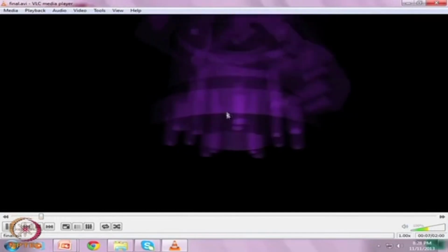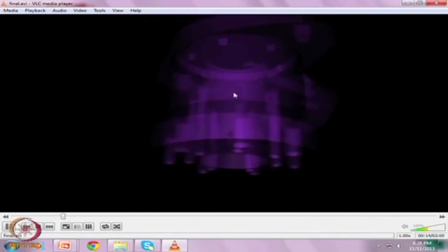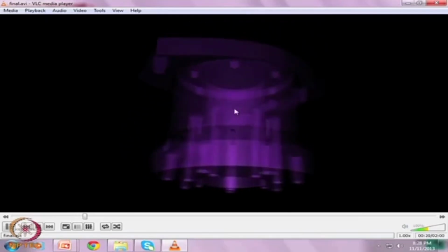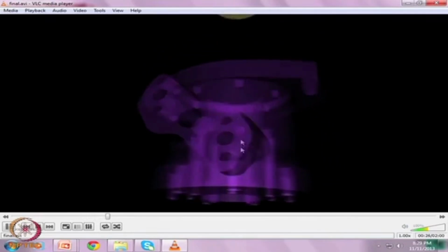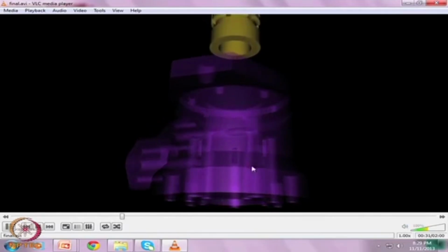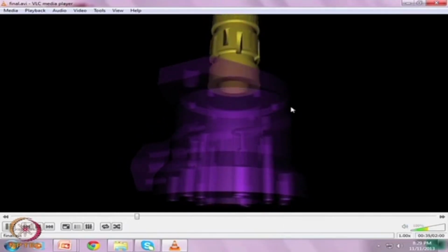In that case, this long hole is the passage to each chamber, and you can look into key-shaped type grooves through which the oil from the distributor valve comes into the chamber and goes back in the same way. You will find 7 such long holes. As well, you will find 7 such short holes for fixing the star ring, etc.